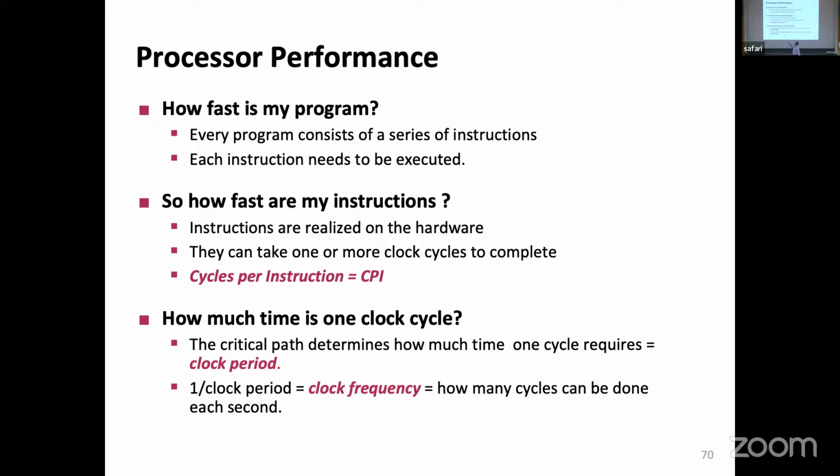And what we define as the critical path is all of these operations that I was making, some of them are more difficult than the others. When you make a load word, you first calculate, you take the register, you add things, you read it, then you read from the memory, then you write back. Whereas some of those, like the jump, was directly, you saw the jump, you already have 26 bits, you add a couple of more bits, and then you have your next thing.